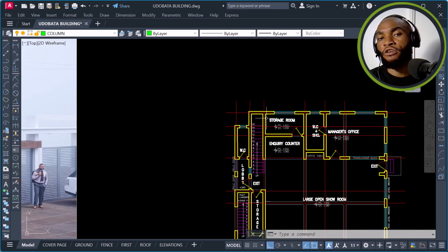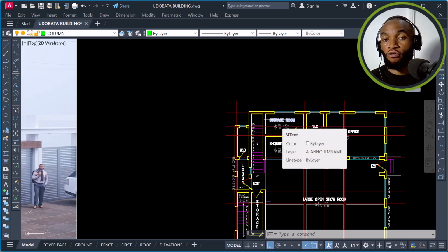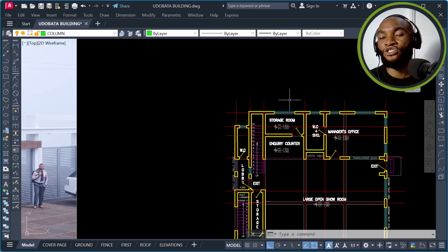Based on this building, which is just a one-story building, I will be assuming a square column first. If there is any failure, and I want the column to still be within the block wall, then I will move to choose a rectangular column. But that will be during the design check. After you are done with the structural analysis and design, we're now going to check each of the members to see if any is failing and also why they are passing, because you must question why you are passing or why you are failing. That's okay.